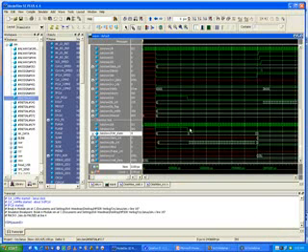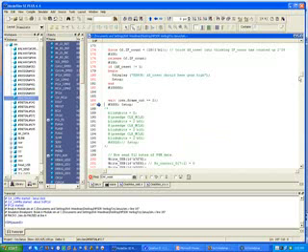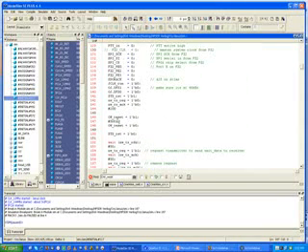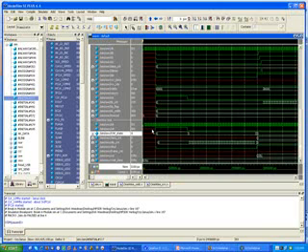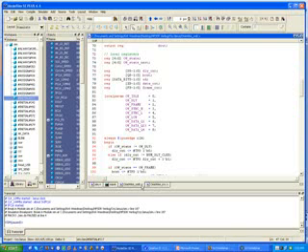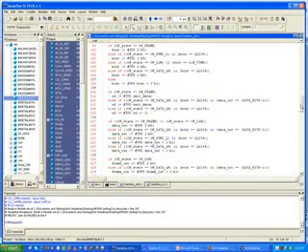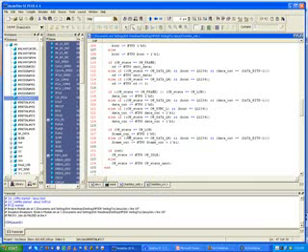Okay, that was generated by the sim.v. If we go back up here, where was that? Right here. I set it high, this is at the beginning of the simulation, delay a certain amount of time, then set it low. And that's what we see right here. Okay, and when reset goes away, you'll see that the state changed from 0 to 1. And why did it do that? Well, we go back to our transmitter, and when we're in reset, where is OW state?